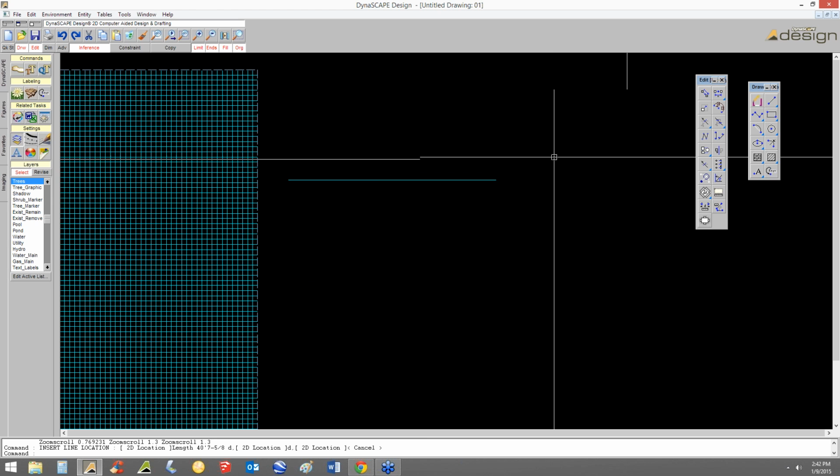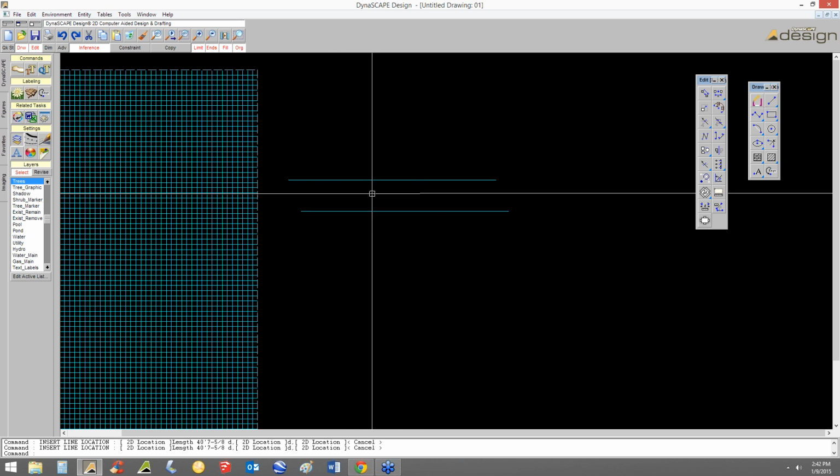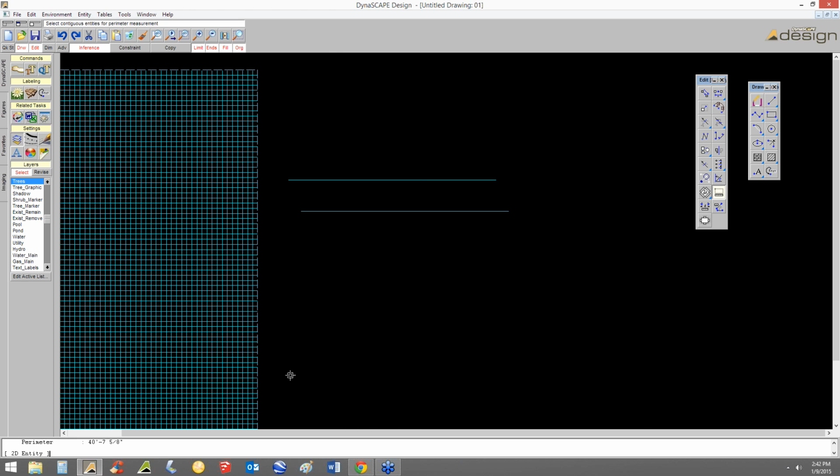I'm going to do it one more time. I'm typing 40 and then apostrophe or foot, then 7, then the dash sign, 5, and then the divided by sign, 8, enter. And there's my line. So we check it by left clicking and right clicking, and there's our dimension. It's a bunch of clicks to do it, but it works.